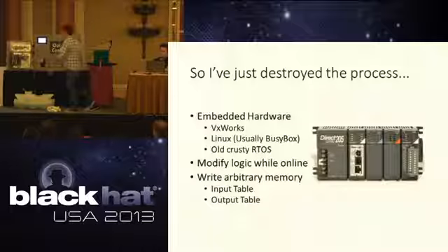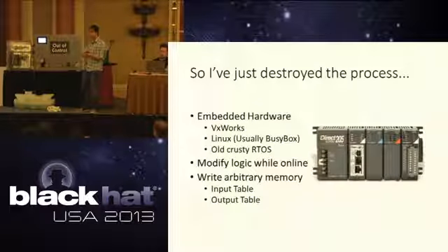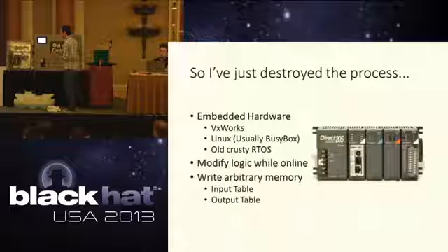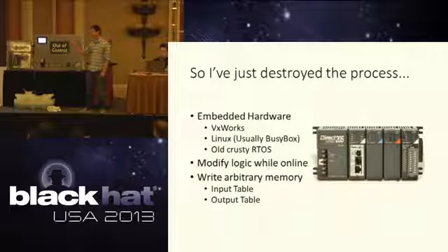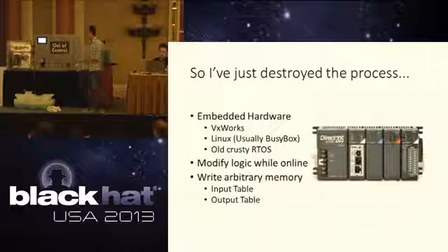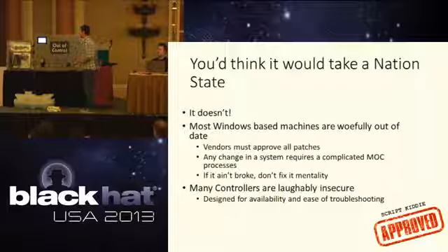It runs VxWorks or some BusyBox distro or some old crusty RTOS, QNX or something like that. And some of them, God forbid, write their own operating systems. But once you're on there, you can actually write arbitrary memory. And we'll talk about what the input table and the output table are in a little bit, but those are extremely important parts of the controller itself, because that's what actually drives these I/O cards and the instrumentation that's attached to it.